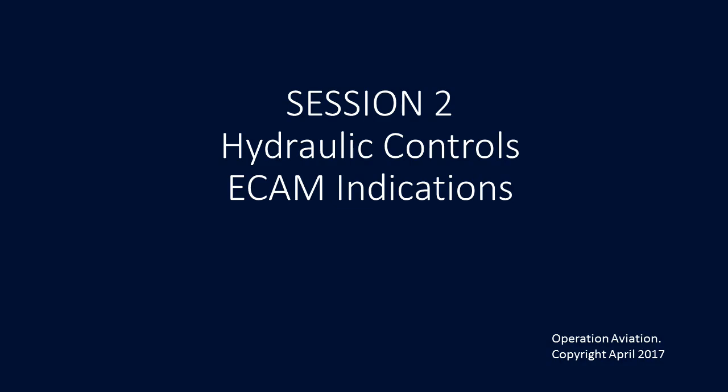So again, a fault is going to appear on the push button when the green or yellow system reservoir has overheated, or also if you have a low air pressure in the reservoir. Just as a side note, the fault indication is only associated with a green or yellow system malfunction. Just keep that in mind, only for the green and yellow, so your main systems.